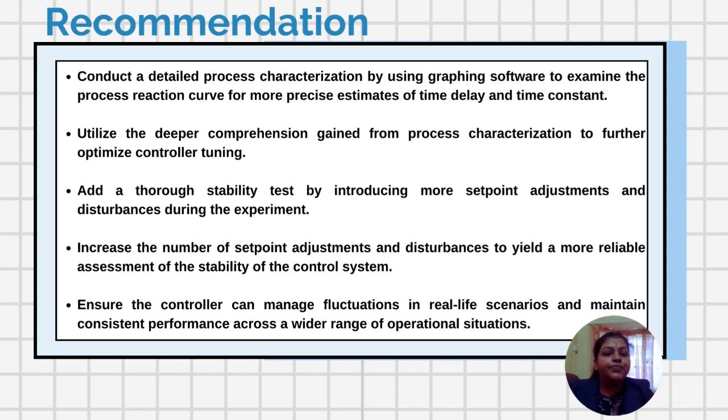Moreover, we can also make a precise estimation for time delay and also time constant. And as for the stability test, we can conduct a comprehensive stability test and also introduce small set point adjustments during the experiment, and also add additional disturbance to assess the stability. So these are the few recommendations that we suggest for this particular experiment.